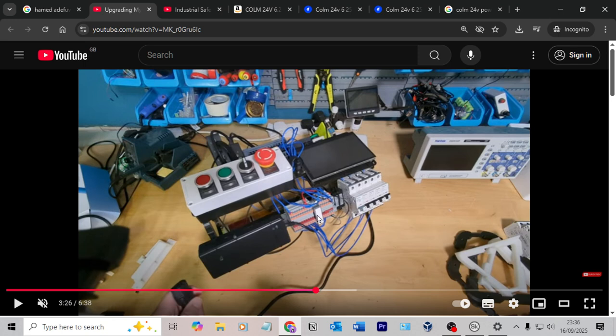Does that then just go straight into these two banks of terminals, or do I actually go to a circuit breaker first? If I do, that circuit breaker shouldn't be positioned there. It should be positioned before the terminals, which would make sense. It makes sense to have a circuit breaker that you turn on and off. So I'm not sure why I haven't done that. I think mostly because I know I control power from this left side. So, one second, let me check.